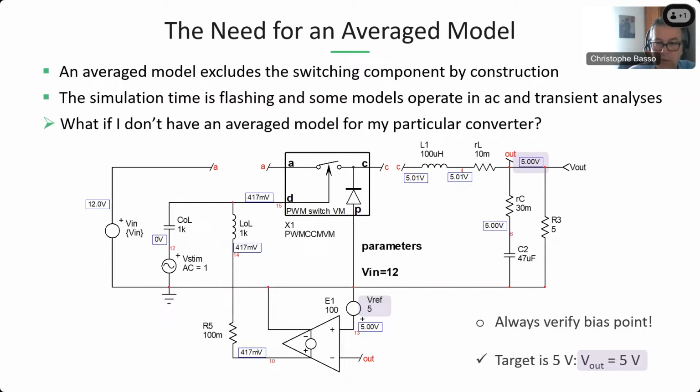An average model lends itself well to determining the frequency response of a converter. So the model needs to match the structure of the adopted DC-DC converter. The cool thing with the PWM switch model is that equations are invariant. It means the structure doesn't change whether you simulate a buck, a boost, or even a forward converter.